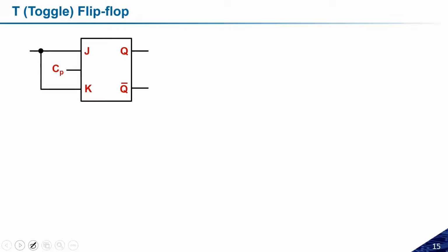If you can recall the D flip-flop, in that D flip-flop we need one inverter. But here we do not need any inverter. And if we don't need any inverter, directly we connect both the inputs, and this will become the T input. Here we will have two outputs, QT and QT complement. So this is how the toggle flip-flop can be made with the help of the JK flip-flop.